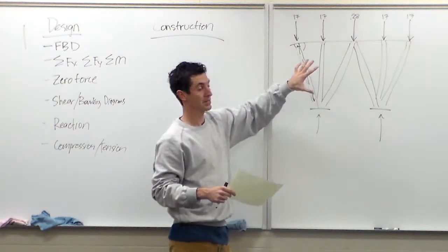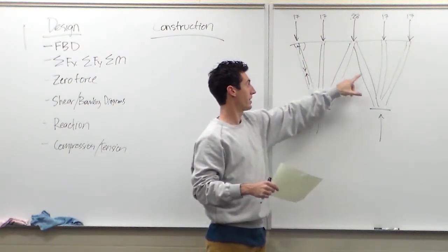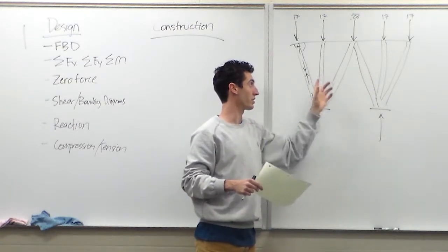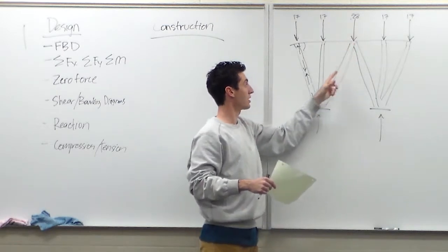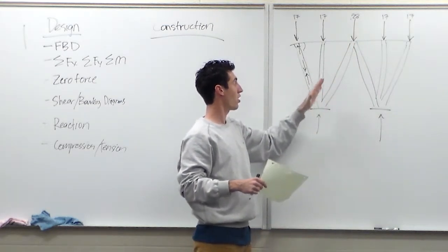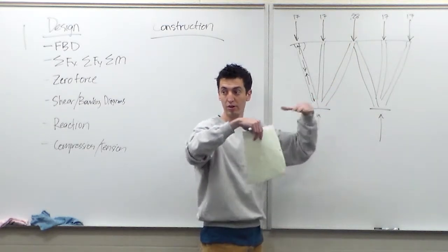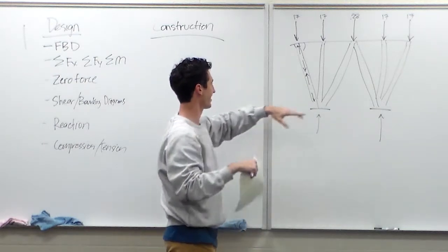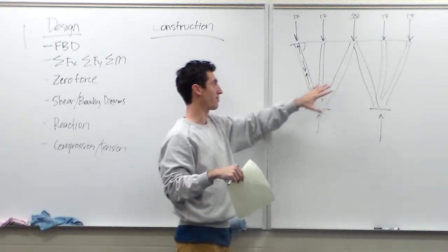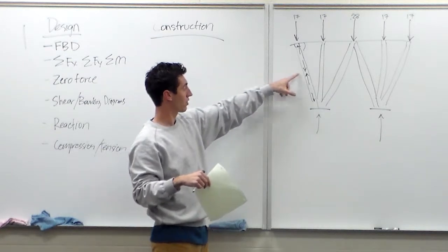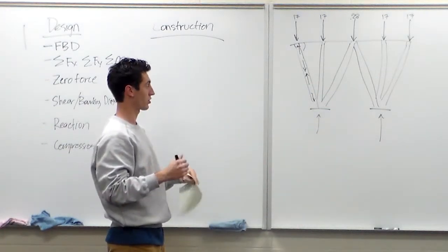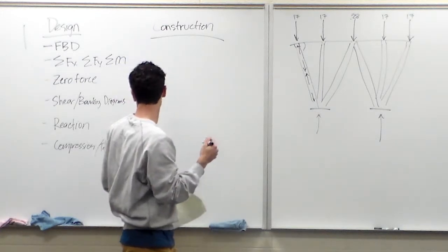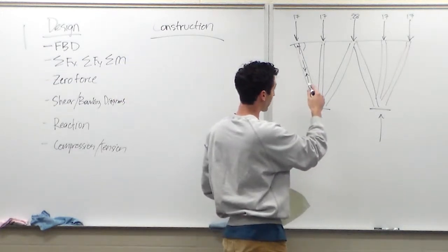5-beam design or a 6-beam design like this, you can calculate the actual compressive force and say, okay, this one and this one is going to be way bigger because it's a bigger load, so we need to make these thicker. They're also longer. They're going to be a little more bendy, and so it's going to break here. We need to beef those up. So based off of your compressive loads and your reaction forces, you can strengthen your design and the construction as well. The other thing that was mentioned is the shear and bending moment diagrams.